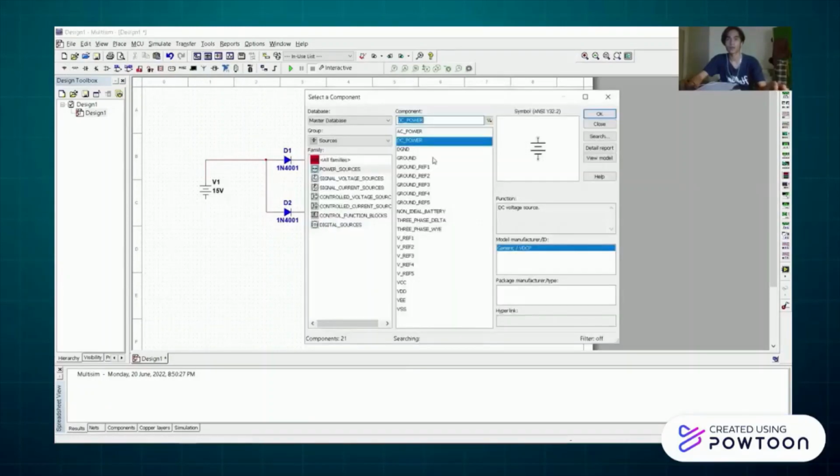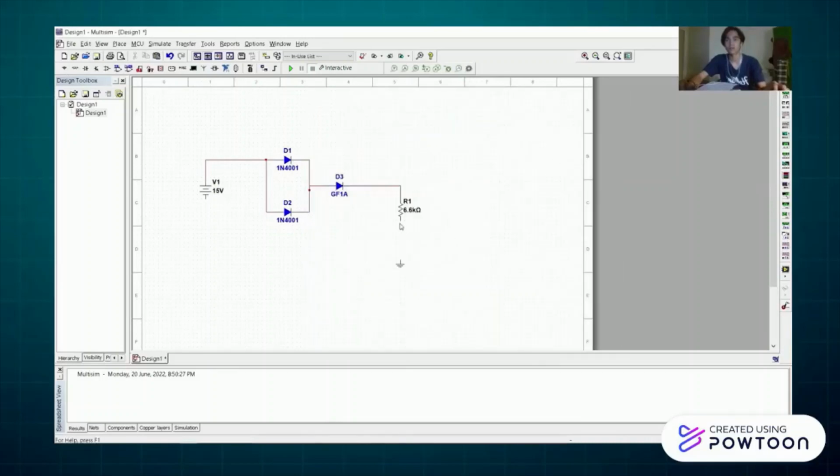The question asks me to measure Vout and ID. I'm going to use 2 multimeters. Take out positive DC power connections with diode 1. Then positive DC power connect to positive multimeter, and negative multimeter connect to diode 1. So this is how to measure a current.